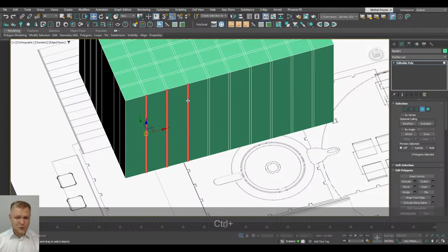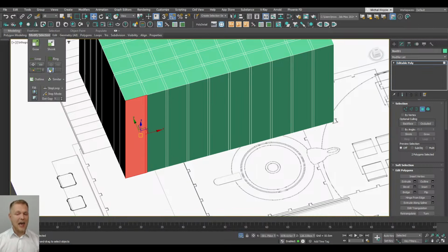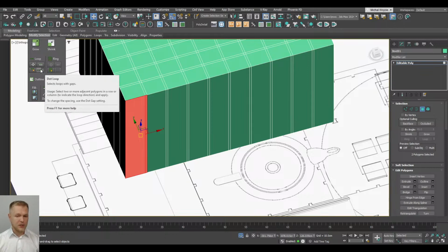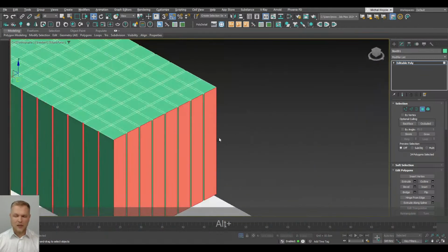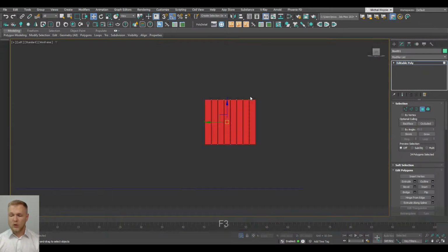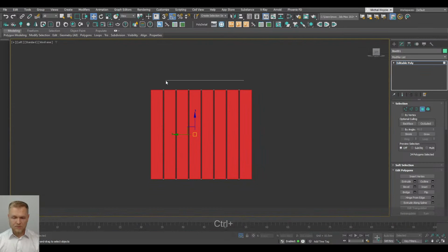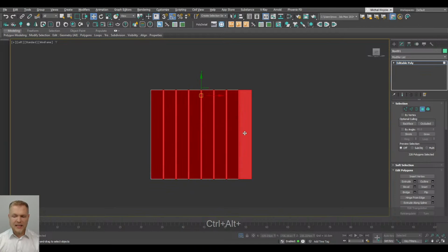And now, we're just going to go ahead and click each line one by one, or we can be smart about it. So we can select 2 lines that we have here and go to our modify selection and select every other one, using dot loop this or ring mode. So if I'm going to dot loop this, you're going to see that I selected every other element. Yes, because it's non-symmetrical, those elements on the side are not going to be as nicely selected, but at least it saves me a couple of clicks. So now we're going to do a trick. I'm going to select this whole, nope, I'm just going to select, yeah, actually we're going to do that, and deselect what I don't need instead of selecting what I need.